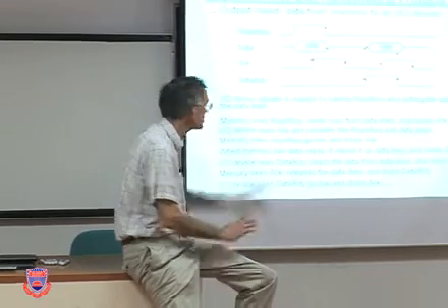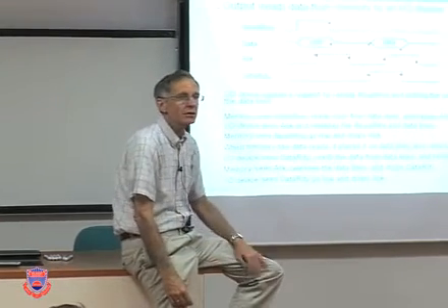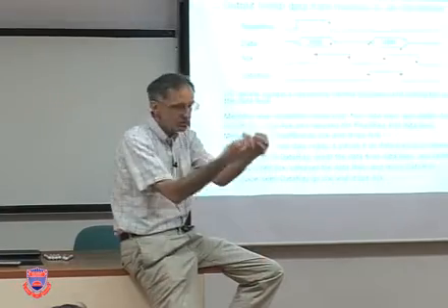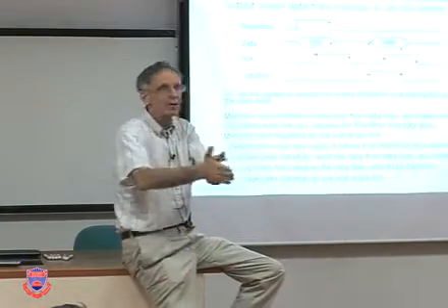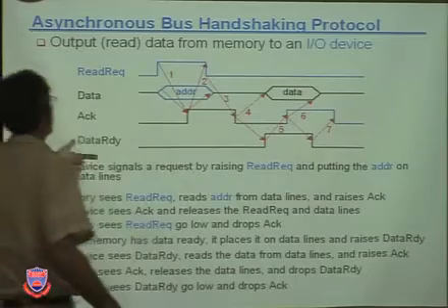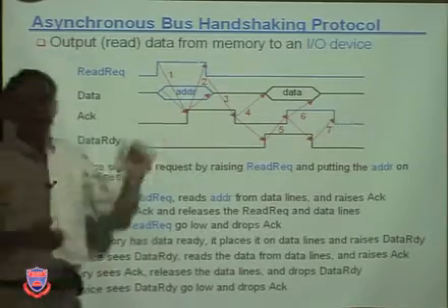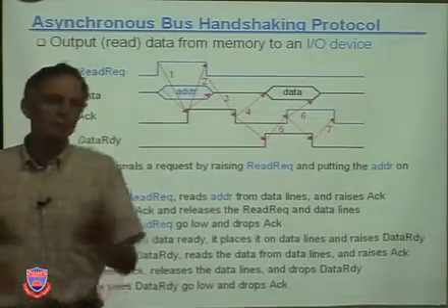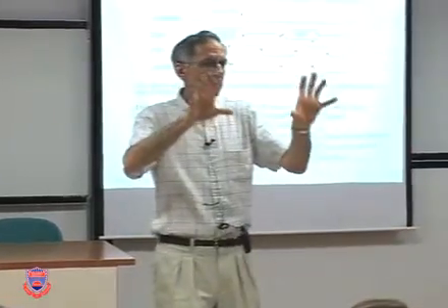Yeah, once you start this chain in motion, you have to finish it. So the only thing you can do then is just throw away the data. Once you start a read, you need to finish it, then you can throw it away. Unless we have another control signal. If we have one more here called abort, cancel or something, then we could use that. If that ever goes high, then both sides forget.